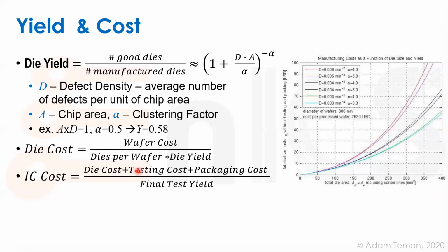If you can't throw it away at the wafer sort and you do another test, you usually always, even if you did a complete test during wafer sort, do another test after packaging to see that the package was connected okay, that nothing happened during the assembly and so forth. So you'll throw out some more dies, but you really want this yield to be as high as possible, or else you pay for the packaging extra. And the testing, so I guess you would have to have in the wafer cost also a testing cost factor and so forth. So these models are very simplistic.